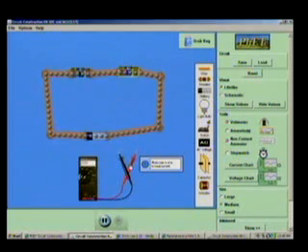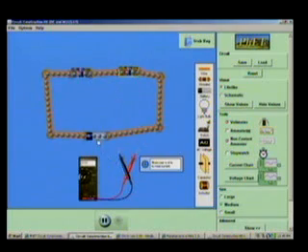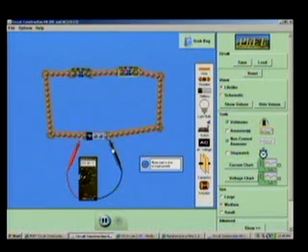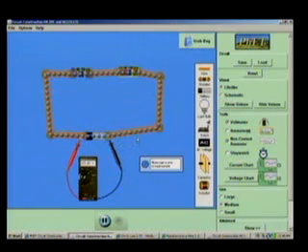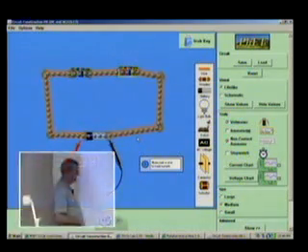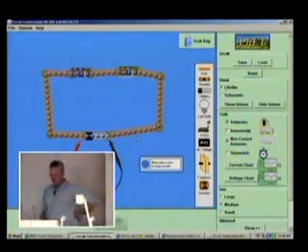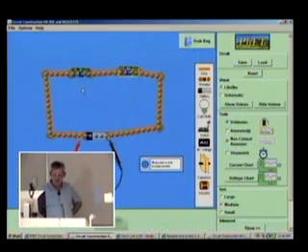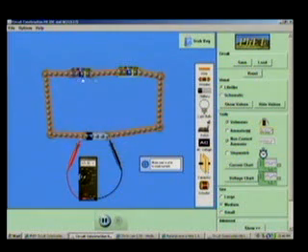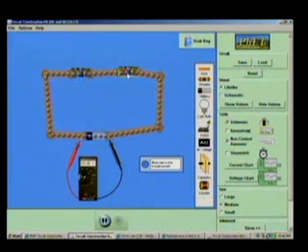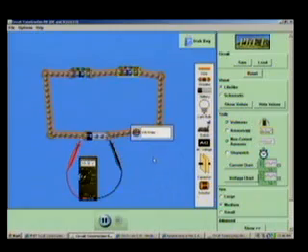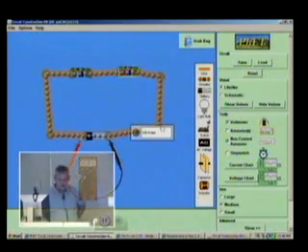I wonder what the voltage is. So what we'll do is put this guy on the positive end, put this guy on the negative end, and see how much charge is flowing. 18 volts between the positive and the negative. All right. Now, here's what we're getting up to. If it's 18 volts, what's the total resistance here? 36. These guys are what is known as in series right now. They're in series resistance. And the amps is 0.5. Okay.